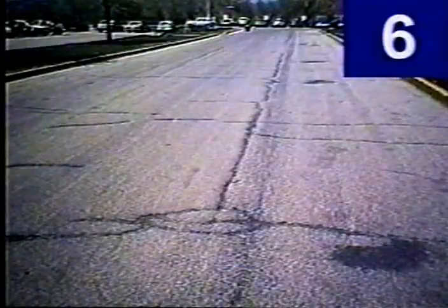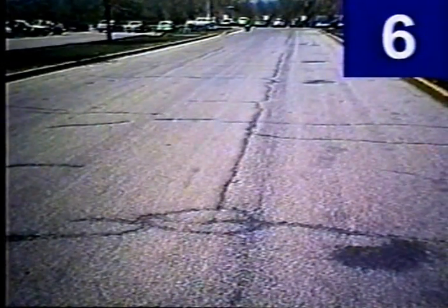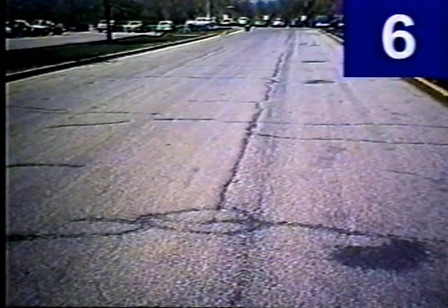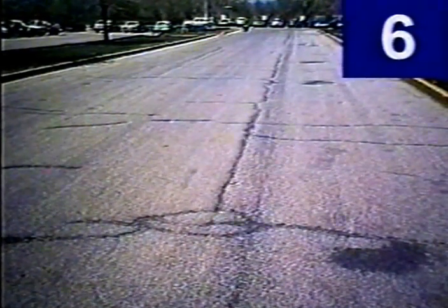If you look at this pavement, at the top of the slide, you can see in the far lane the first signs of block cracking, another indication of pavements that would be candidates for surface treatment and would be rated as 6. And block cracking, more extensive block cracking, is very evident in this pavement, an excellent time to put on a preventative maintenance treatment like a seal coat.